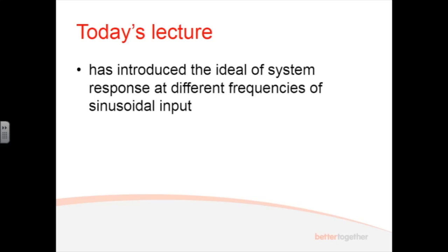So if you've dialed into your power station, I want 50 gigawatts please, and it's sitting stationary at 50 gigawatts, and you think, I've forgotten what the transfer function of this thing is. I could inject a very low amplitude sinusoid into that system, so it could vary between 49 and 51,